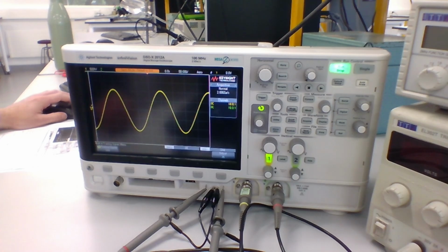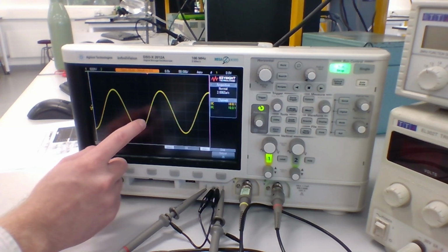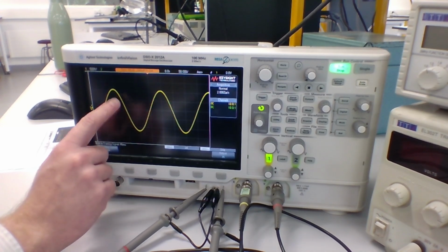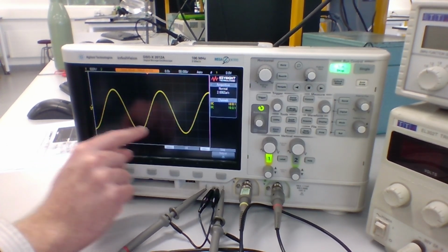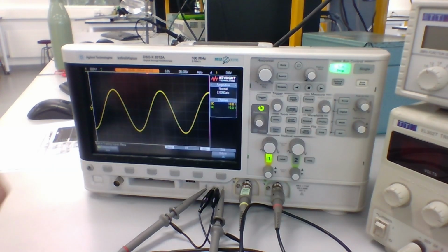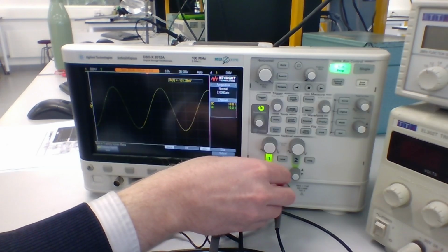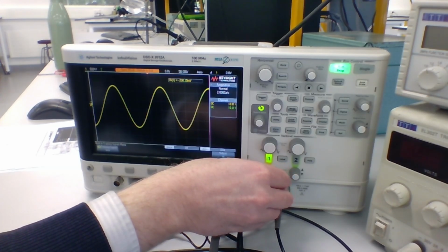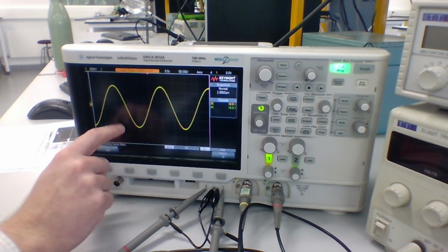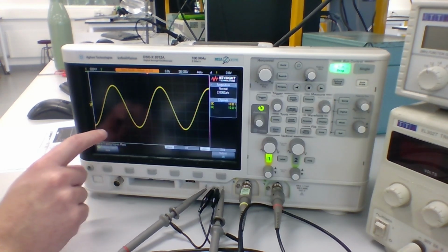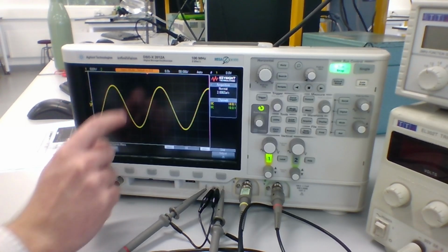Similarly, we can also measure the voltage of the signal as well. In this case, we probably want to adjust our signal on screen. Ideally, we want at least one of these peaks or troughs to be aligned with one of these grid lines, which makes our measurement a bit simpler to do. So we can move this up and down vertically. For example, I can move the signal so that the trough is aligned with this line here, and then I can count up grid lines to estimate what the actual voltage is, knowing that there's 500 millivolts between each of these large grid lines.